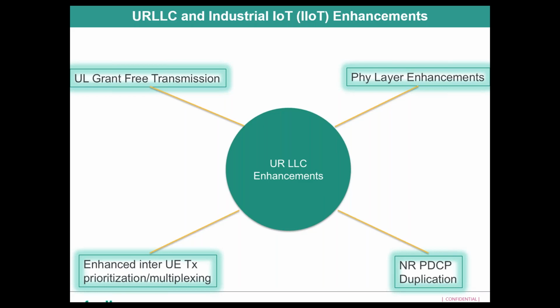You can have 15 kilohertz subcarrier spacing all the way up to, for FR1, 15, 30, or 60, and in case of FR2, 60, 120 to 240. But as your subcarrier spacing increases, your TTI, your transmit time interval, reduces, right? So you can send a lot of data in a much shorter time frame, right? And as you know, in 5G and our frame structure, we don't transmit per frame, but we're able to transmit on the order of the OFDM symbol, which is a big plus for 5G and our frame structure, right?